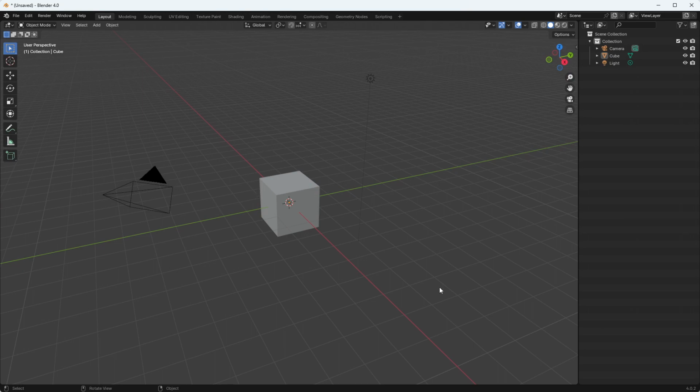So the first thing I do in a 3D view whenever I get one is I press T to hide this toolbar. I'm just tapping T back and forth. You can unhide it with T as well. I don't use those buttons to pick my tools. I just use the hotkeys because it's so much faster. And if you do it that way, it's going to make you very slow. The only one I use from here is measure sometimes.